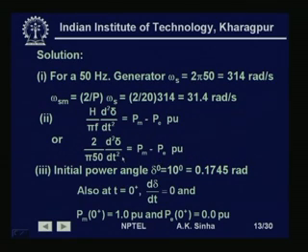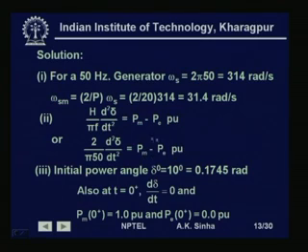So, we can write down the swing equation for any machine knowing its inertia constant and the frequency and if we know these powers, then this is Pm is equal to 1 and Pe whatever is the output. If there is a difference, we are going to get an acceleration. If these two are equal, the acceleration will be 0, the speed will remain constant.